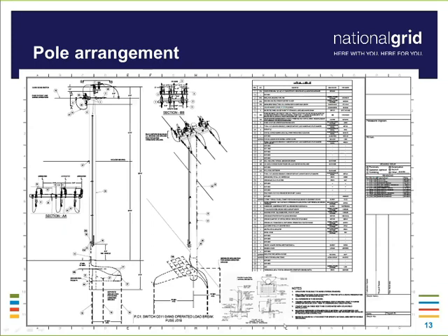Also, typically, with a pole drawing such as this, it would reference back to the overall site plan. So from the site plan is where you can initiate your sections or your views in respect to what this pole arrangement looks like. And then we can tie those two drawings together through all the detail provided here at the pole drawing, tie that back to the site plan, so we would know exactly where this pole lies, what equipment is going on the physical makeup of the pole, and based off of the tie back to the plan view, we should be able to tell what direction this pole is intended on traveling.